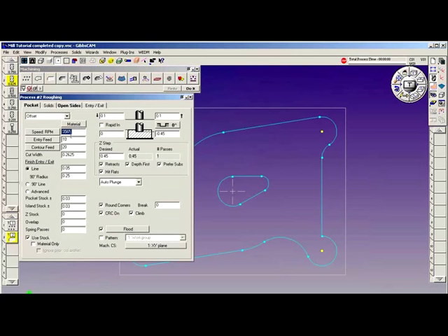The feeds and speeds, I'm going to go ahead and take the speeds down a little bit to 2139. My entry feed looks good at 10, contra feed at 20, not bad. The cut width, 0.2625. You wonder where that value comes from?